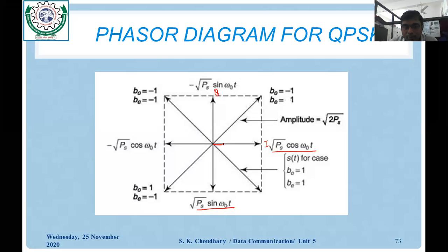So basically this is the carrier signal, the red line I have underlined. The combined symbols would not be available on these axes; they would be in between the in-phase and quadrature axes. That's why it is quadrature phase shift keying. This is the first symbol, which you can refer to as 1 0. The first bit, 1, is the even symbol, that is 1, and 0 is the odd symbol, that is -1. Then again 0 0, when both symbols are negative, -1 volt.